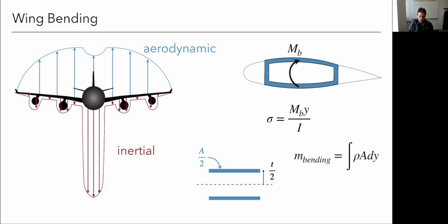So if we take these two equations and assume this case where, let's say, every section is as efficient as it can be, meaning we didn't put any extra material more than we just barely needed. So let's say we're right at the yield stress. And of course, this is a simplification because we're only considering bending, and really we'd also consider shear, torsion, and the other loads on your plane. But say just bending, we're right at the limit of just yielding. So we could solve this, we put in what I is in terms of A, right? Moment of inertia in terms of these areas. We solve this for A and plug it in. What we're going to find is that the mass is proportional to the bending moment over the thickness.